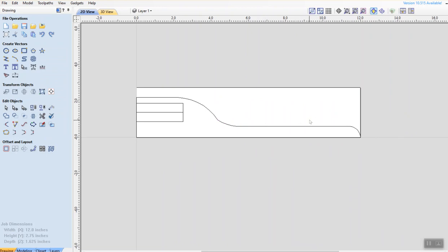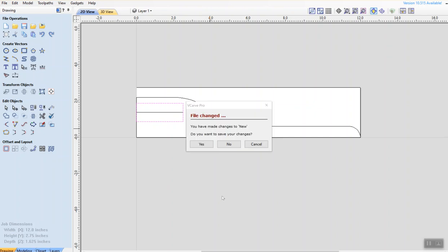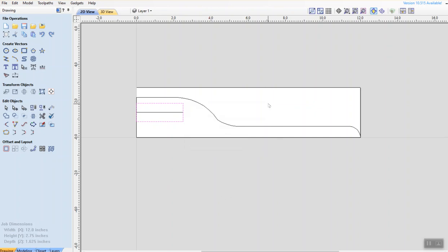But the whole point of this is that it has to be a closed polyline. I don't even need this anymore, the center line that I generated earlier, so I can erase it now. Sorry about that. Cancel. I'm going to press the delete key. You don't need this anymore. Delete key. So those lines are individual lines, as you can see, and we need to join them together.